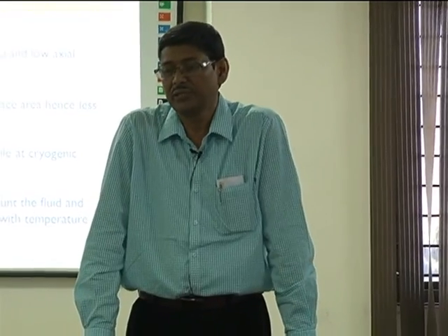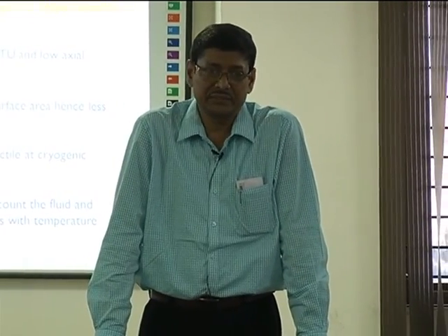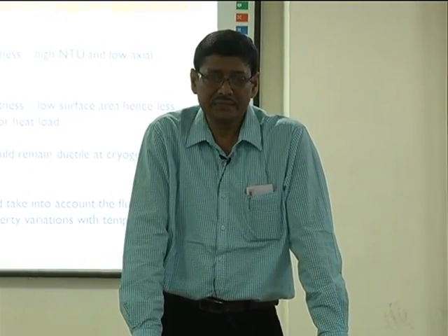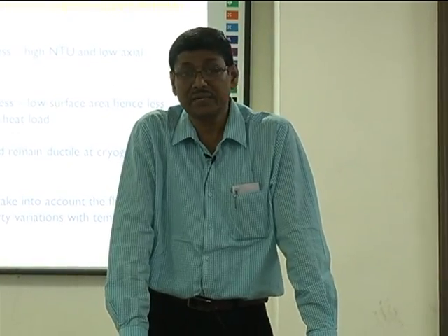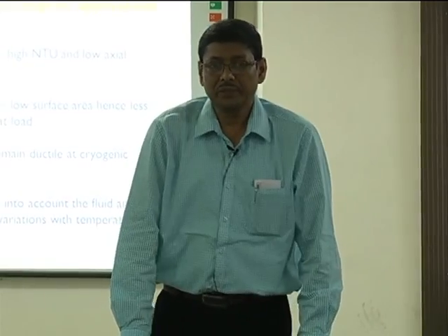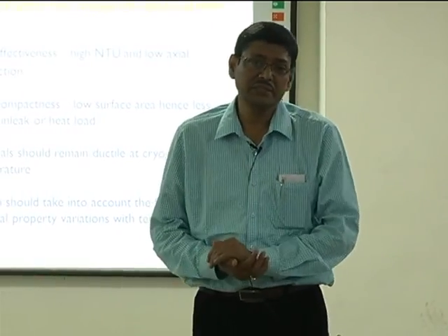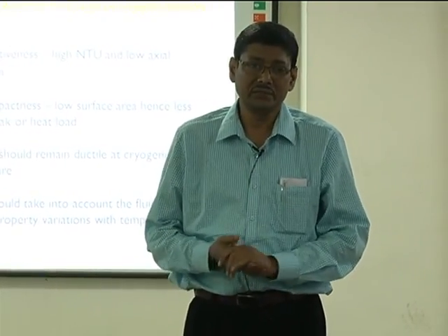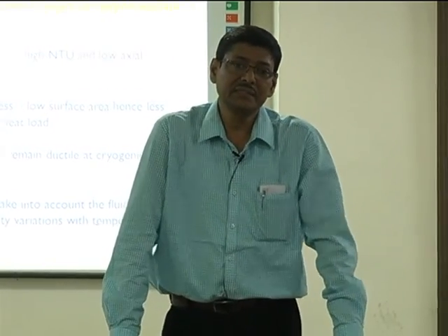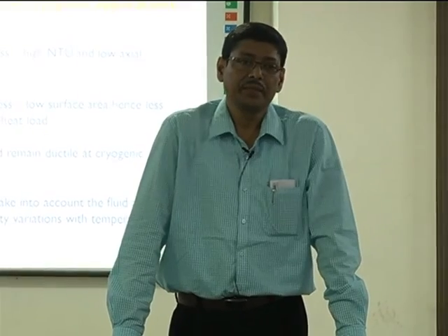I hope many of you know the Joule-Thomson expansion process, by which we generate low temperature. This is one of the processes for producing liquid gases, or liquefaction of gases, but there are many other processes. Now, particularly for this Joule-Thomson process, if you look into the simple thermodynamic calculations, it says that if the heat exchanger effectiveness is less than 85%,